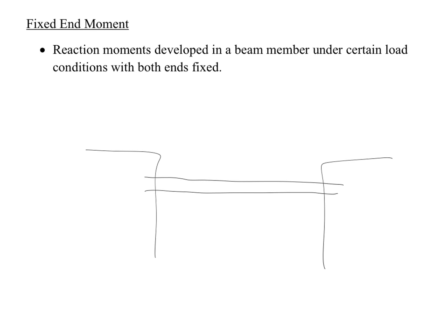You apply force on a structure, even if it bends 1 times 10 to the negative 35th meters, it will bend a little bit. The idea here is that at the ends, you have what are called reaction moments. So if this pulls down, the end of it wants to react to cause it not to bend that way, so it's a moment that you would draw like this. And on this end, it would look like that. So these are called reaction moments, and the idea is that this bridge wants to pull down, the actual cantilever beam rotates back and pulls back against it in this direction.